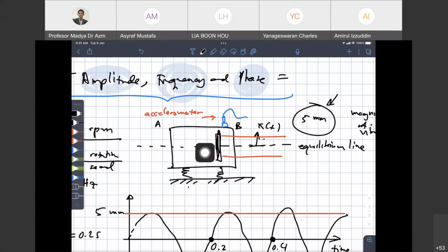With this type of machine, you cannot say by eye. For very big piping vibrating at low frequency, you can see by eye how the pipe is moving. But that is the case of a very big structure moving at low frequency. For this kind of machine, the motion is a bit high frequency. It's not 2 hertz, it's not 1 hertz, maybe it's more than 20 hertz. So you cannot see by eye how the machine is moving.